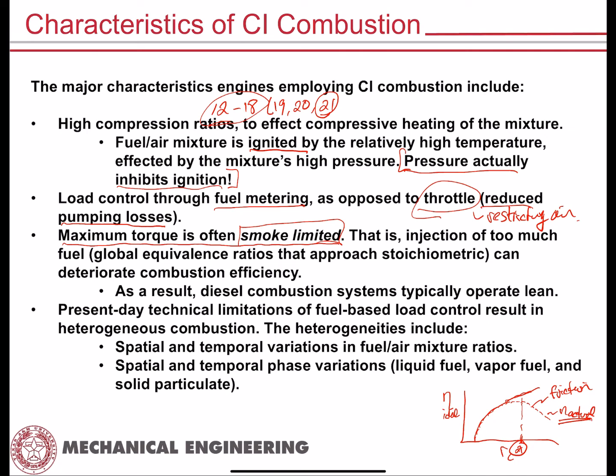And instead what happens is you end up starting to basically pyrolyze your fuel, okay? In other words, you create little char particles, or what we scientifically call soot particles, okay? So soot is basically what we would call a pyrolyzed hydrocarbon or a fragmented hydrocarbon, right? In other words, that hydrocarbon underwent a chemical reaction, not necessarily an oxidation reaction, okay? And so you take this C18 long hydrocarbon chain and you subject it to a high temperature where it basically fragments into some radicalized complex form of a hydrocarbon that stabilizes itself as a soot particle, okay?